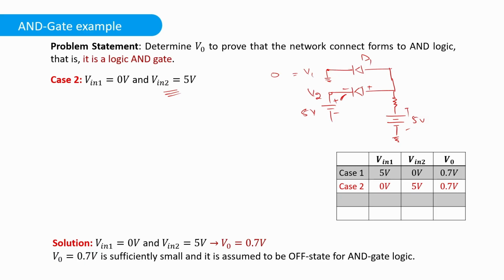So remember that whenever opposite terminals are connected with each other, for example, for this case, we have this diode connected with the battery source, but the terminals are opposite with each other. So this is a reverse bias condition. Okay, so if this will be reverse bias condition, then what happens is that at this point we will have an open circuit, right? Exactly like this. So this is 1 kilo ohm, this is 5 volts. So for D2 we have open circuit.